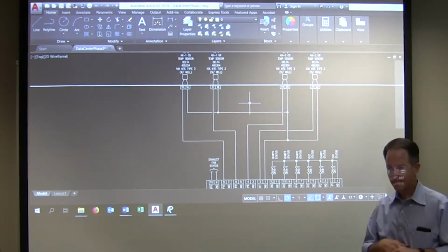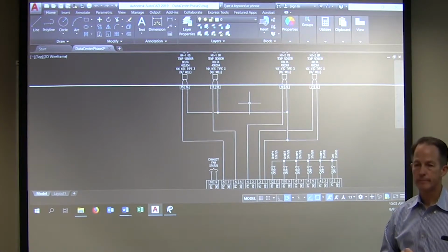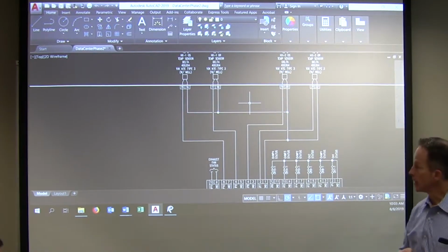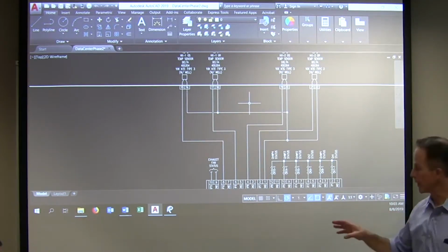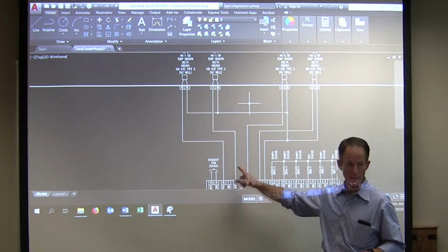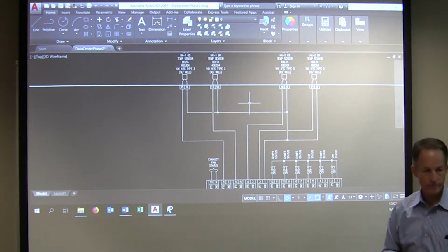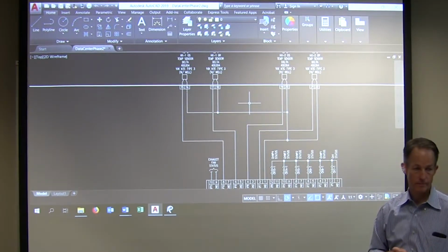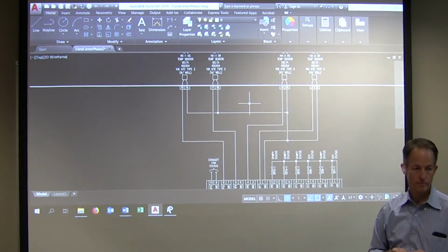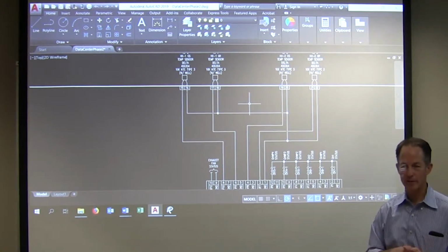So we had a few of those where the points they brought out were the wrong ones, so it wasn't changing even though the room was getting really cold. Instead it was warm, we just put the wrong point on there. Yeah, and I've seen that, or in the configuring of this device, this is input 10, but somehow I put 9 instead, and 9's looking at something that shouldn't be, and so then you don't get things working right. A lot of times you're talking about initial setup, but there's times after the initial setup that the outside temperature and the temperature in the room have been constant, and you find out later that something's changed down the road, and you're like, how did this not get caught? Once in a while it's like 3 years down the road, and you're like, how has this operated for 3 years and no one's ever caught this?